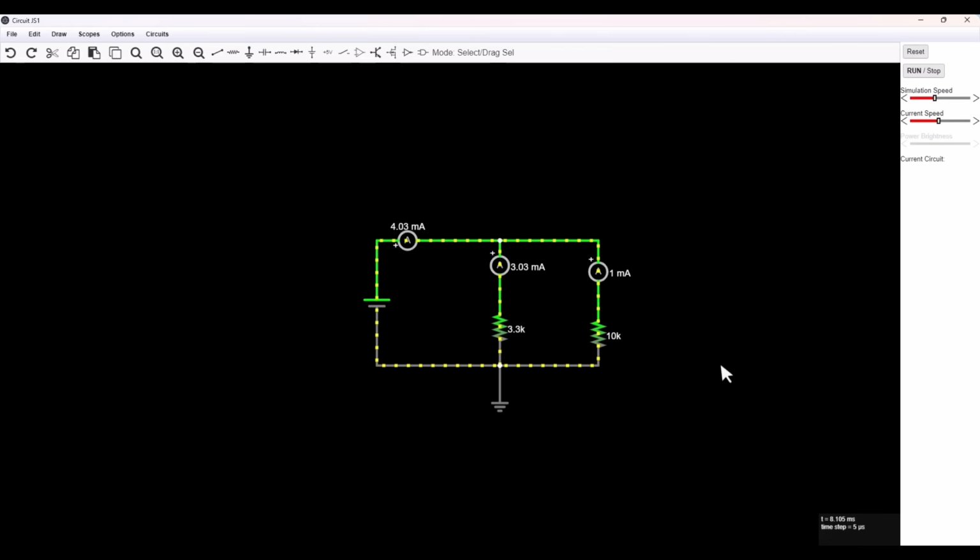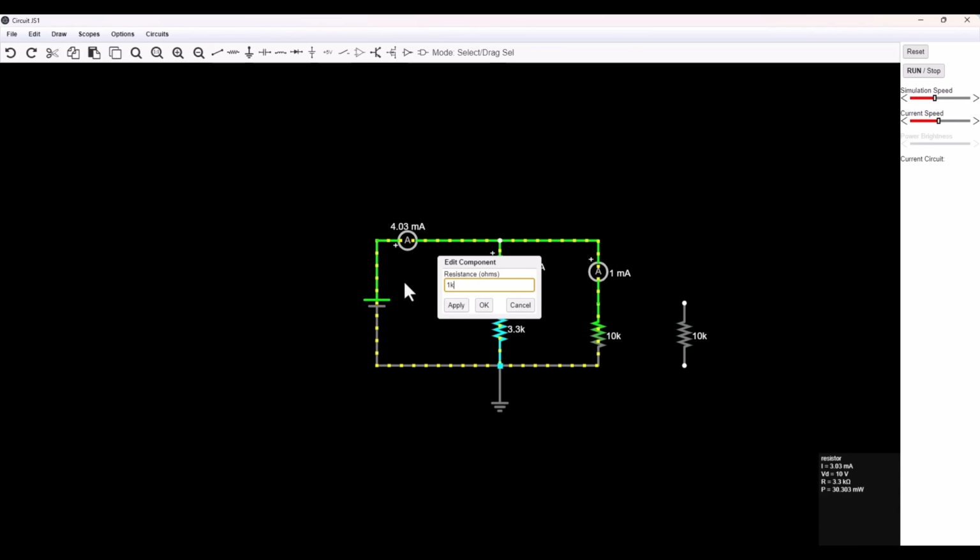So for the next one, we do have 3 resistors in parallel. It means that we need to copy only one of these guys like this. So 3 resistors, 1K. Let's just change it to 1K. Then we do have another resistance. The R2 should be 2.2K. Then the final resistor should be 5.1K. Cool. We do have that.